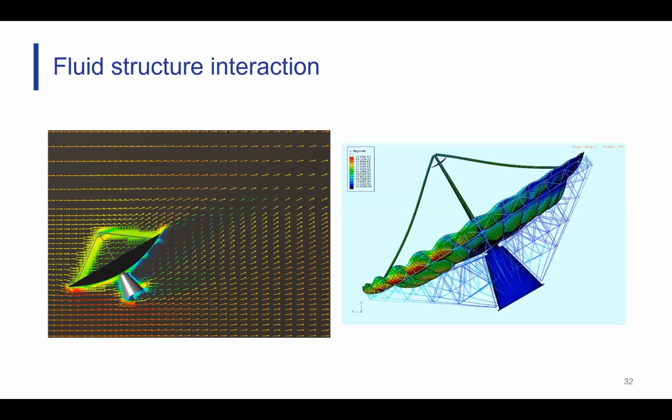Again, complicated terminology. All it means is basically the deformation of a physical structure with response to internal or external flow. So here we can see pressure forces acting on the satellite dish and deforming its surface. Why this is important is because fluids can cause oscillations. Some of you may be familiar with the Tacoma Narrows Bridge accident in the 40s. That's kind of the textbook example of how structures can fail if you don't consider the effects of fluids acting upon them. Another thing, aircraft wings, turbine blades, that can break pretty easy if you don't consider fluid forces.